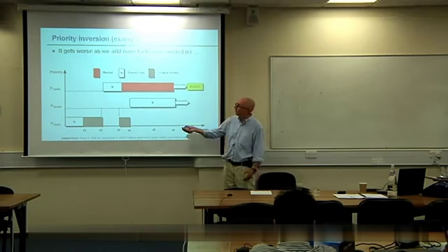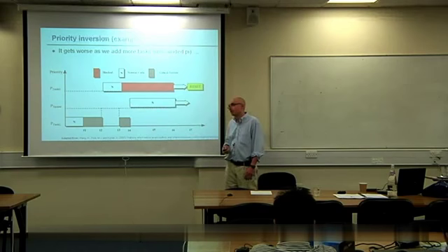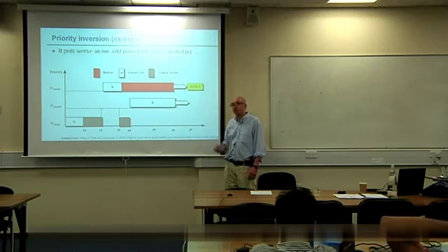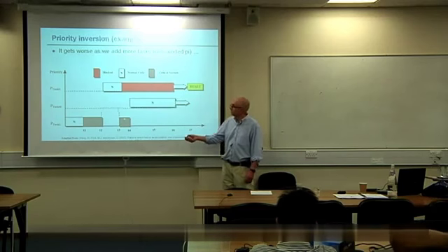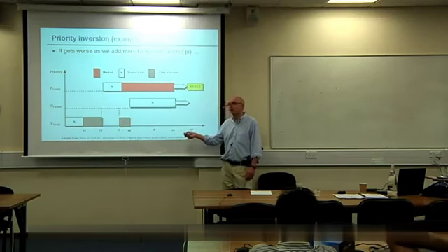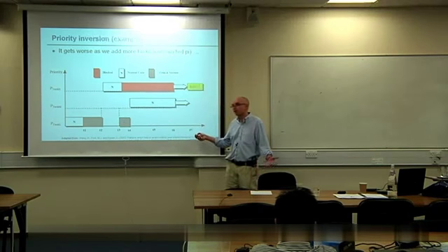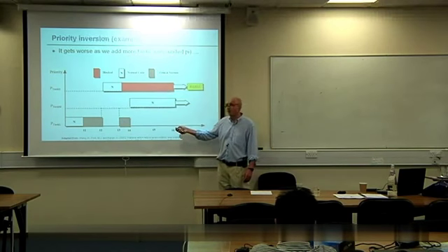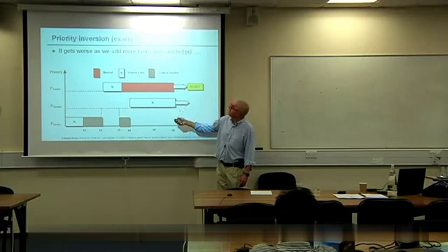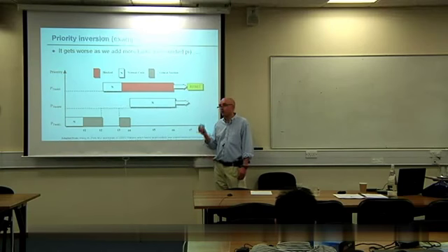But then, unfortunately, a medium priority task comes along. Now it's all normal code, no critical sections, so there's no reason why it should not interrupt the low priority task. That's the logic. Now what's happened is we've got really serious priority inversion problems happening in this design.